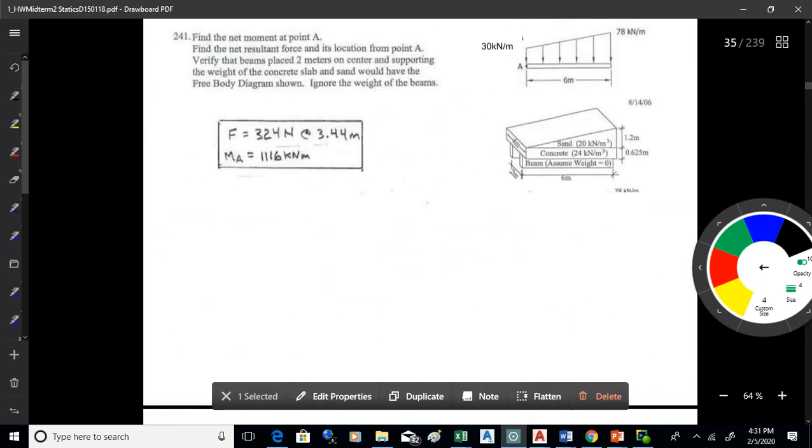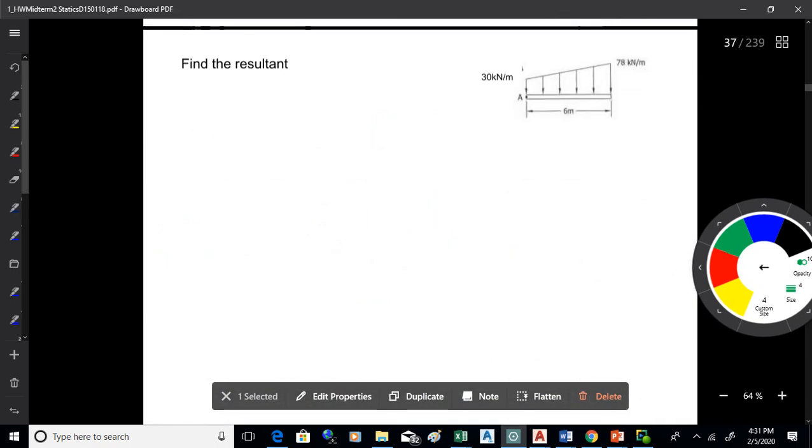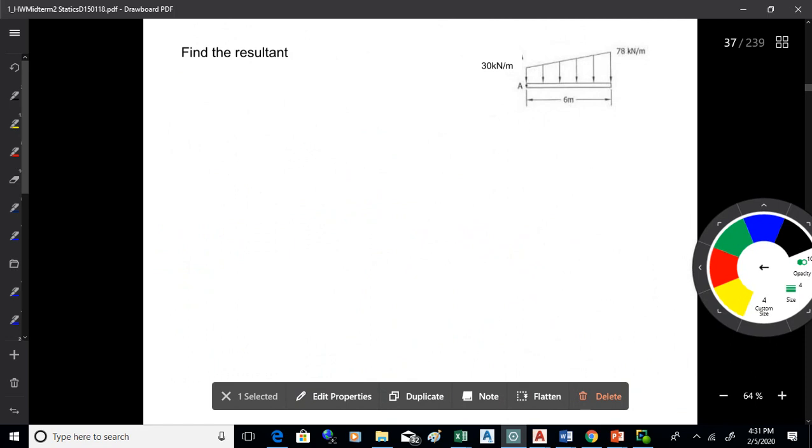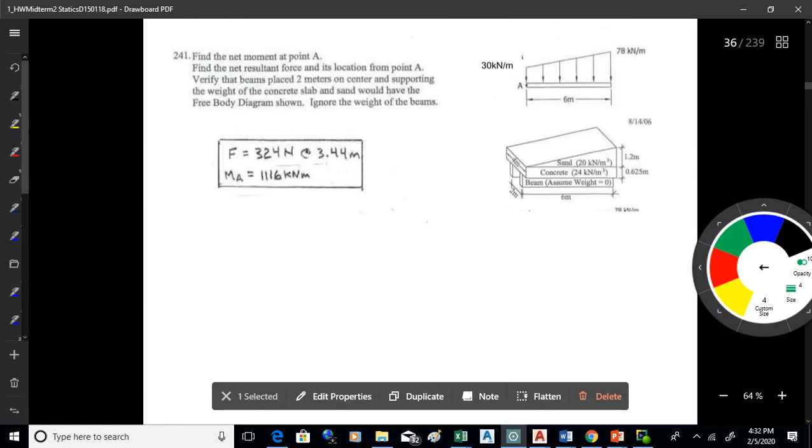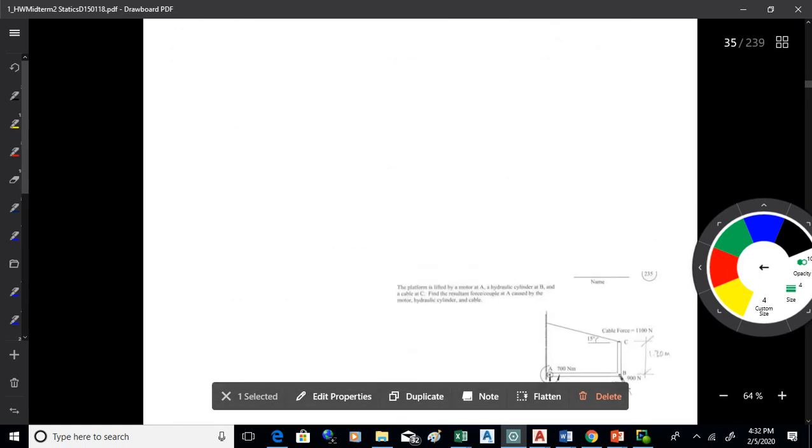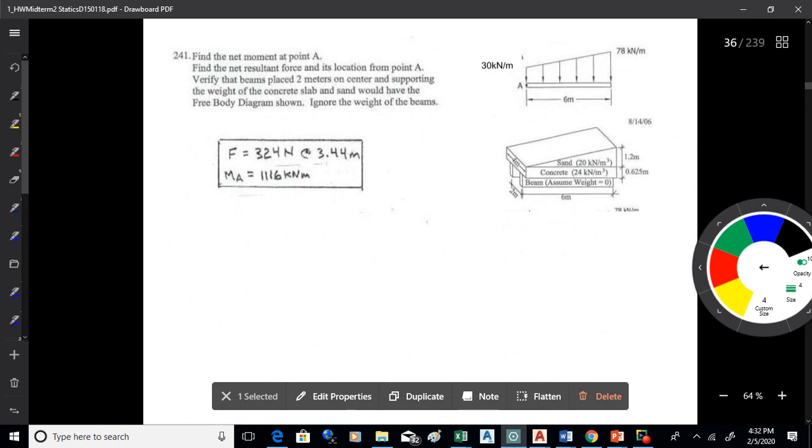Okay. All right, now let's look at the step after that, which I put on the top because that's really the more standard statics type problem, where you find the resultant. Now here's where you start doing the half for the triangular area and all that. You're going to take that shape and break it up into pieces because you want to find an area, which would be the load, and then put that area at a centroid. So you need pieces for which you can find centroids.